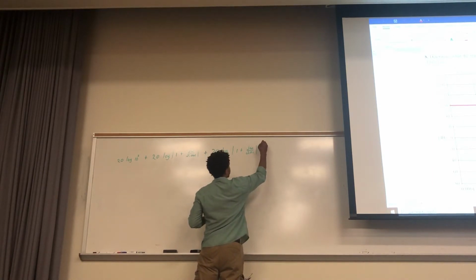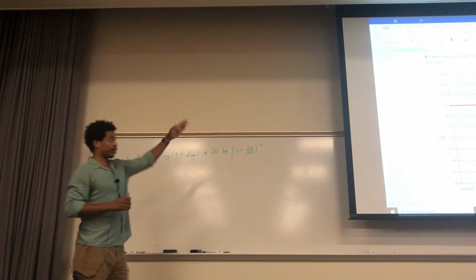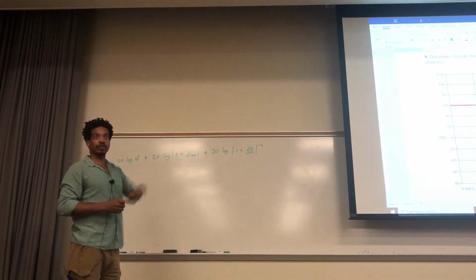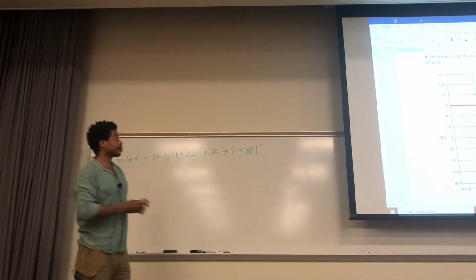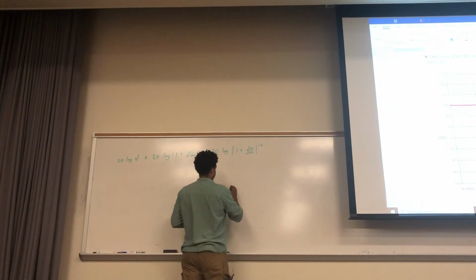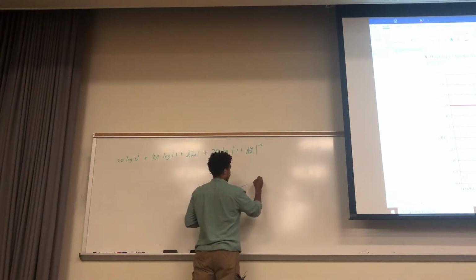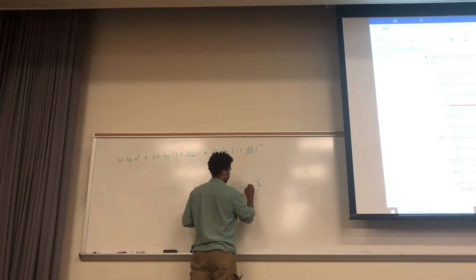But it's -2 because it's dropping down 2 slopes. You see those 20 decibels per decade slopes? What I mean is, we have that first one. It would continue off like this, but first you drop it down 20 decibels per decade once, and then we have to drop it down again, another 20 decibels per decade, to end it right there.